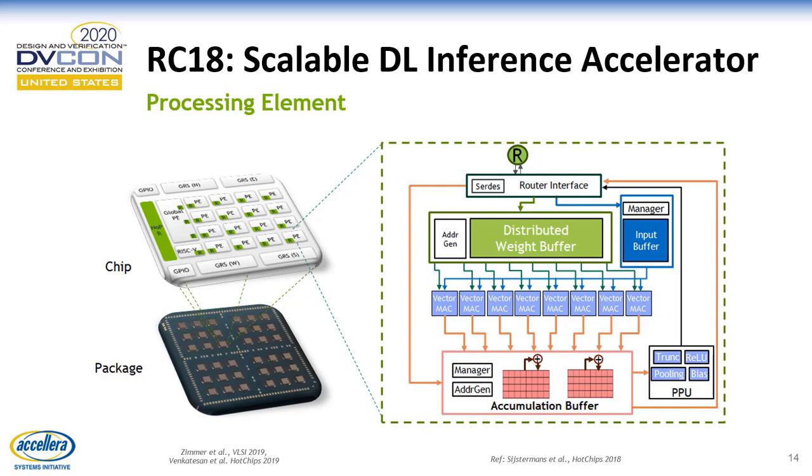In order to achieve scalability, we enabled partial sum reduction both temporally within the PE as well as across the PEs, and therefore the partial sum values from the accumulation buffer can be received from or sent to the neighboring PEs using the routers. Once we perform all the required partial sum accumulations, we use the post-processing units to perform the truncation and other post-processing operations and finally store the data back into the global buffer or the global PE. This design used a number of MatchLib components, and we were able to make fast iterations and ensure that this is designed at a much lower design effort.